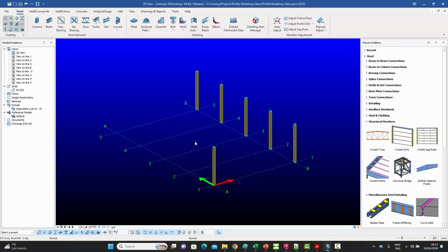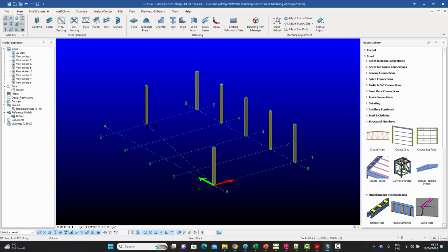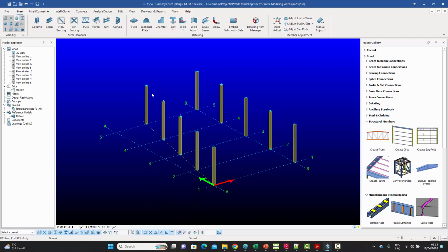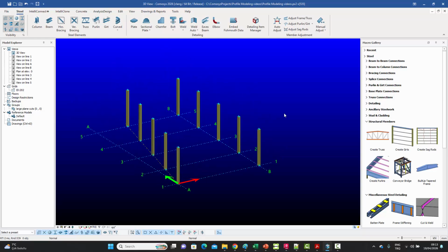But for this one, we first need a construction line. So let's create the construction line. It was 4.5 meters offsetted from there. So we'll hover over this point and say DX 4,500. And then we'll just come in and snap to this point. And now that we have that line, we can go in and create our other columns like that. And once we've done that, we can just go and match them to that as far as the direction of the columns is concerned. So that was pretty simple, just getting the columns inside.